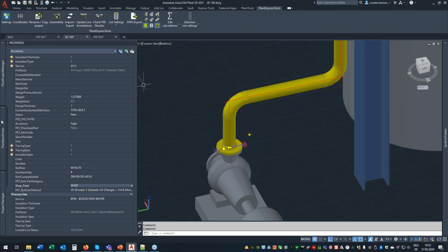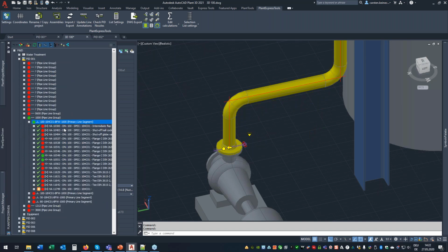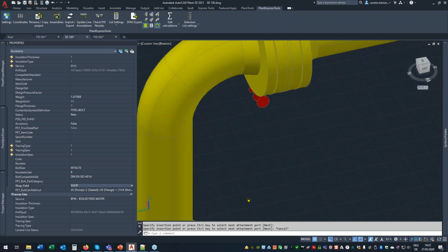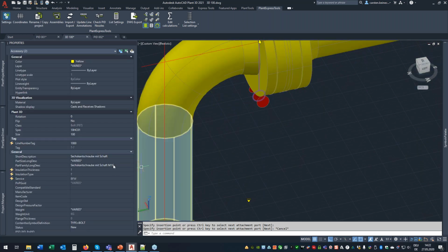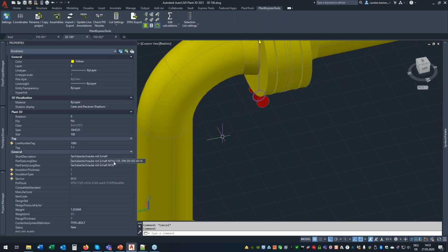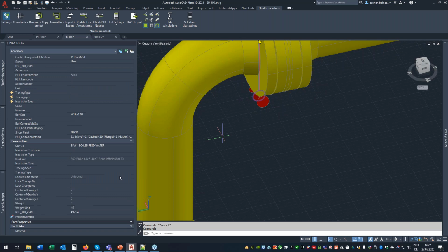If I insert, for example, some flap or some wafer flange or a valve, then if you look at the data here, we now get, that's not the bolt. Okay, now we get M16 times 130. And if we want to see the calculation, so this is 52, and then the gasket, the flange, the gasket, the flange, and again, nut, two washers, protrusion, and that adds up to 120.8.